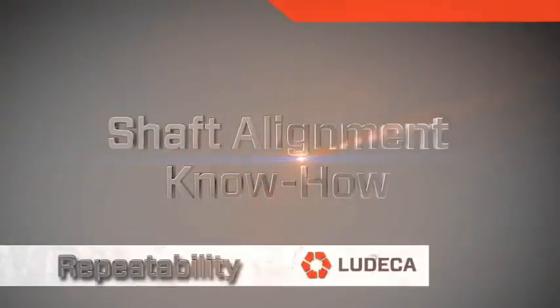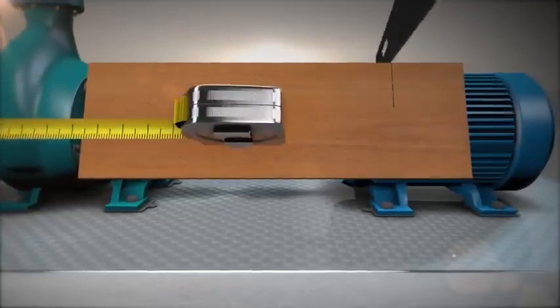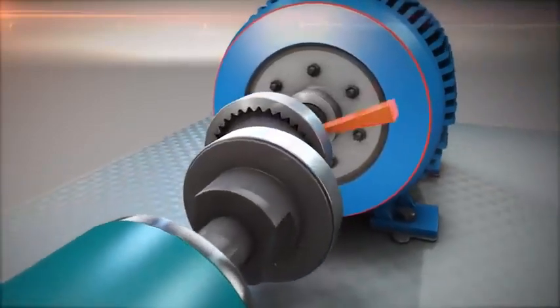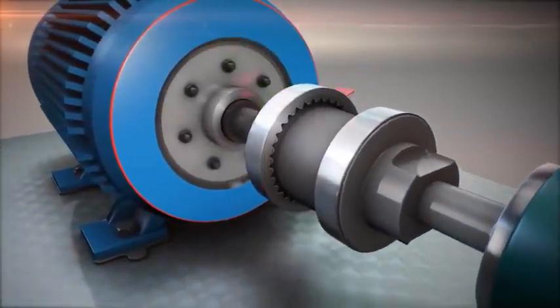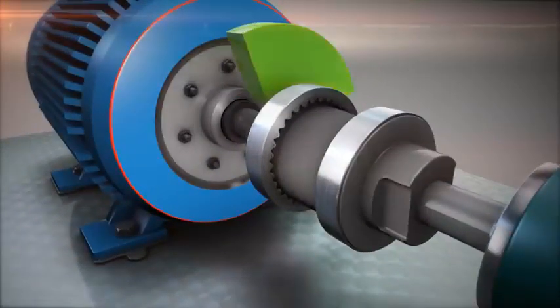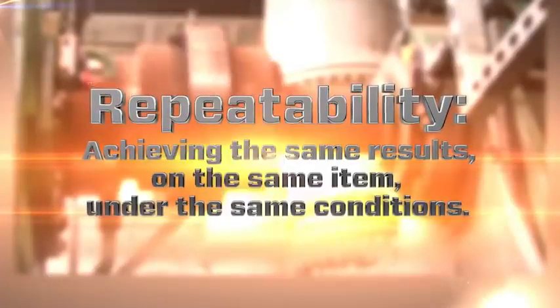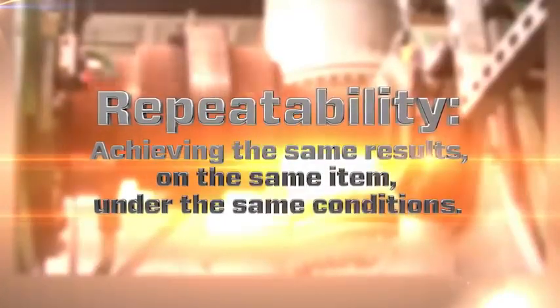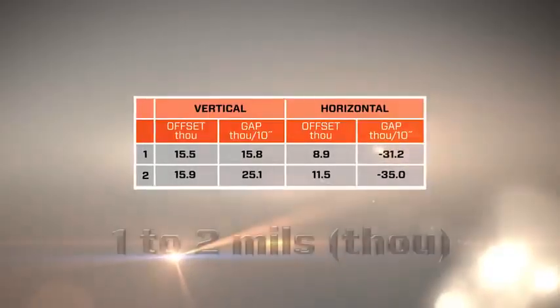Shaft alignment know-how. Repeatability. We have all heard the old carpenters saying, measure twice, cut once. When we start a shaft alignment measurement, we take two sets of readings with the same start and stop positions, following the natural rotation of the machine. This way, we make sure that the needed alignment corrections are precise. We call this repeatability. It means achieving the identical measurement results in the same way, on the same machine, under the same conditions. A measurement table helps to keep track of these measurements.